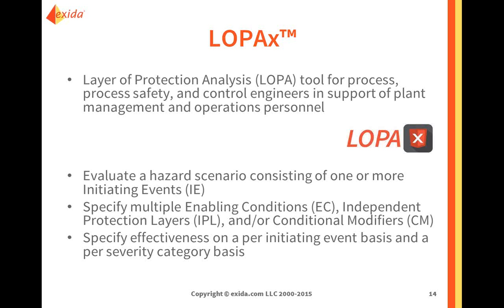And if you have specified a risk tolerance, the LOPA tool will also be able to calculate resulting risk reduction factors. If you identify something as a potential layer of protection, for example a safety instrumented function, and you want to know how much risk reduction that function needs to provide, you can calculate that as well. And I will show that to you in a little bit.